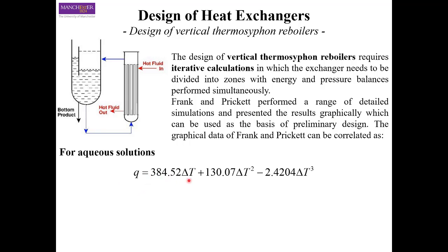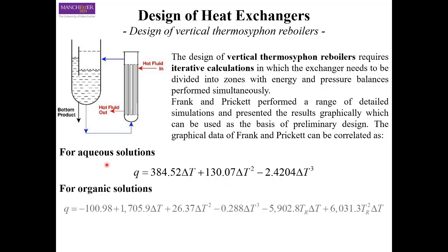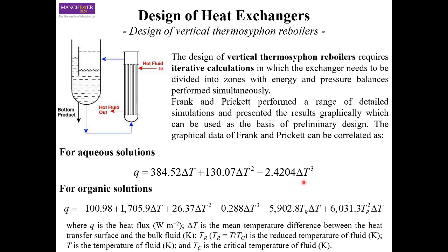Okay, and these are all the constants in their equation. And if you have an aqueous solution, you can use this equation. But if you have an organic solvent, you have to use an even more complicated equation here, where delta T is the mean temperature difference between the heat transfer surface and the bulk of the fluid. Then you have another term, TR, that comes from thermodynamics.